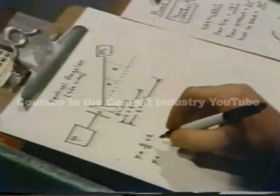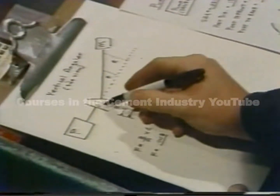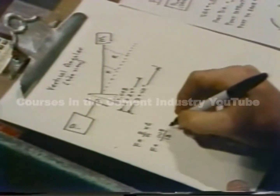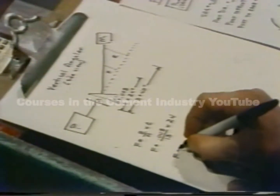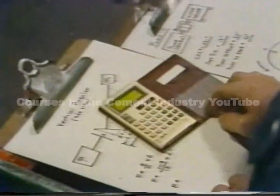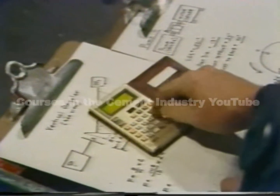Now, B, of course, was the amount of misalignment measured, and that was 0.008 of an inch. A was the diameter of the post that he measured earlier. It was 13 inches, and C is the distance to the front feet, which is 24 inches. The result of this equation will be how much movement or change must be made to the front feet. A calculator can be handy to make the computation. He clears it before starting.